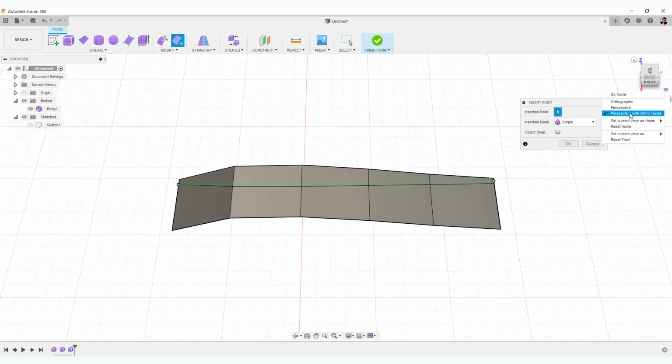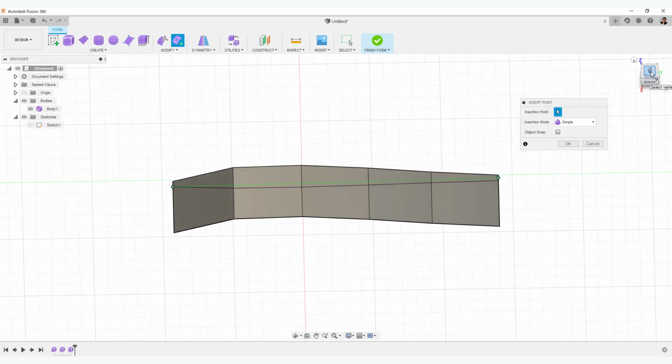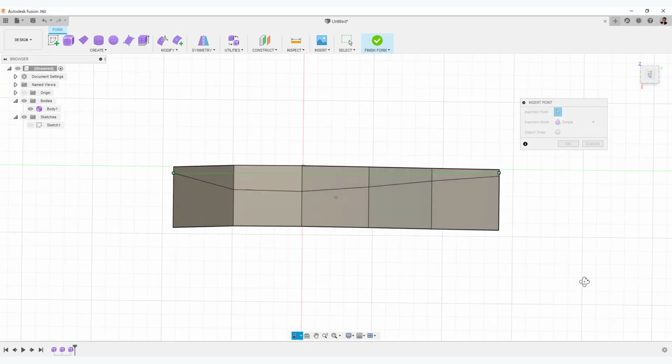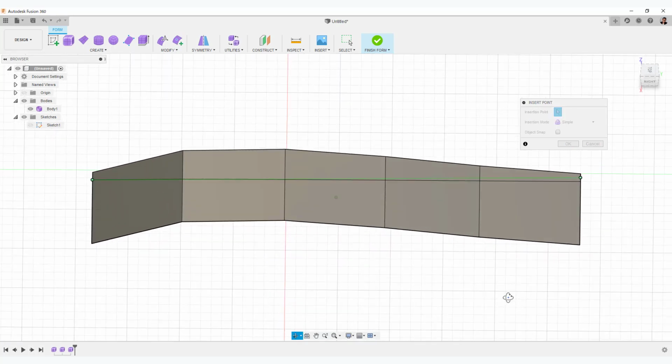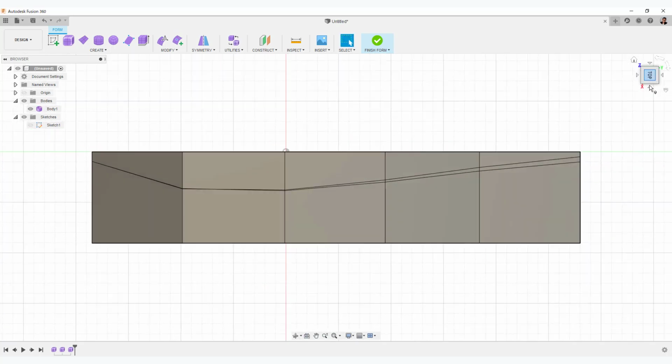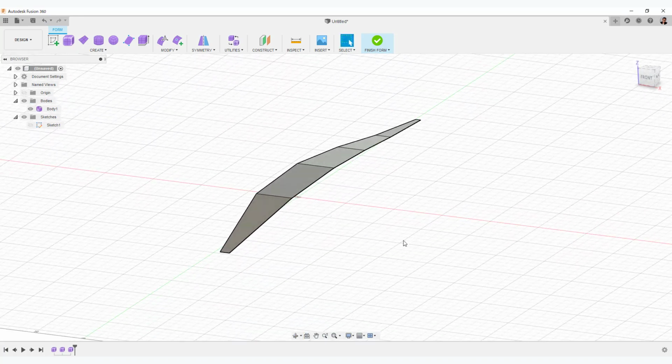Select orthographic on the view cube if you want to accurately project the line. Then move the view like this to project the line when it comes to the target position. One thing to note at this time is to make the block display and project the line. Delete unwanted edges. Double-click an edge to delete unwanted parts.